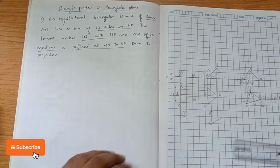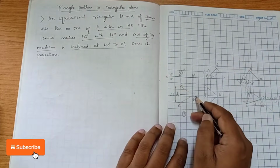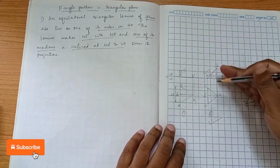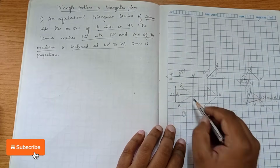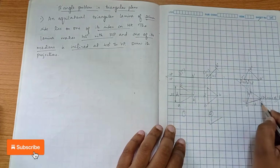So this is what the problem is. You understood the procedure, right? After constructing these 2 positions, we have to draw the medians, that is BD1, the first median, and BD, the second median. So we draw a 40 degree angle line. After that we mark a point B. First we will measure BD1, this median length, and cut the arc on this 40 degree angle line.